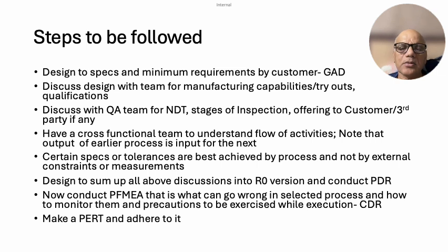Similarly, by using different techniques in welding, or by selection of the right processes, or the right edge preparation for welding, or by sequencing certain activities of welding and then machining and then heat treatment and then welding, we may be able to achieve the tolerances.